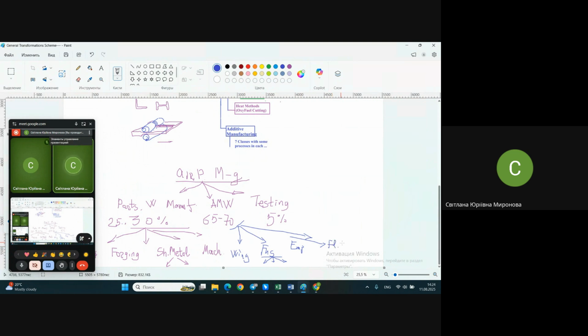In case we have composite materials in our airplane, we additionally need one more separate shop. Because when it comes to mechanical fastening, when we're working with metal and metal fasteners or welding, it's one group of processes. If you have composites, it's already another group of processes, and all this variety of composite materials. In our standards, composite material parts are considered parts. But what is happening inside the composite material shop is really an assembly operation. They have special tools for forming the layers of composite, and very special equipment for it.